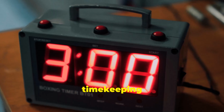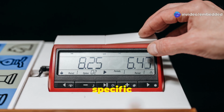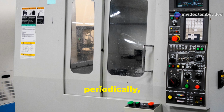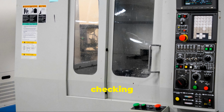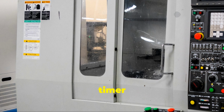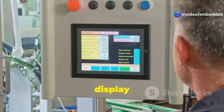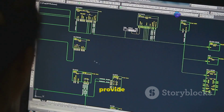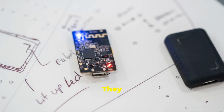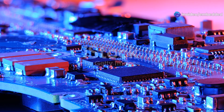Timers provide accurate timekeeping in embedded systems. We can configure them to generate interrupts at specific intervals. These interrupts allow us to execute tasks periodically, like updating a display or checking sensor readings. Timer interrupt example: configure timer interrupt, void timerISR, update display. State machines and timers provide a structured approach to managing complexity in embedded software. They enable us to create systems that are modular, maintainable, and predictable.